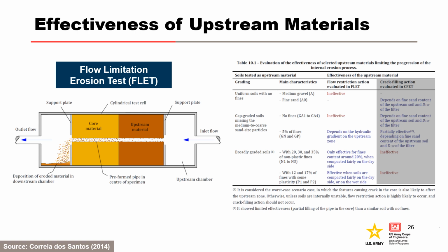Some tests have shown that soils compacted fairly to the dry side are likely to restrict flow, mainly due to their self-healing abilities. However, it should be noted that this observation might not be valid in soils with highly plastic fines. For the tested gap-graded upstream materials, hydraulic loading is critical. For soils with 5% fines, the plasticity of the fines is also relevant.